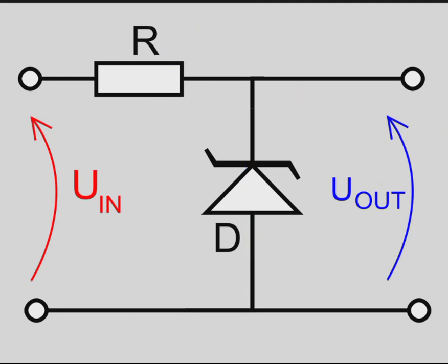On the other hand, it cannot be too large. If it is chosen too large, there will be a large voltage drop across this resistor VR, and then the Zener diode may come out of the reverse biased region. If the voltage across the Zener falls below its breakdown voltage, that is VZ, it will not conduct the current, and the current will decrease and it will come out of its turn on mode.